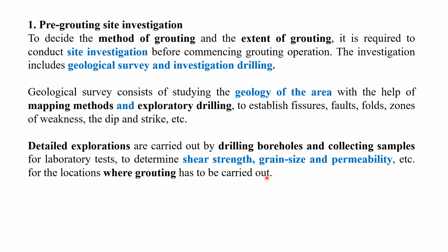So depending upon these requirements, we have to go for the detailed explorations. That means we have to make boreholes and collect the soil samples before grouting. What is the shear strength, particle size analysis, permeability also we have to know.